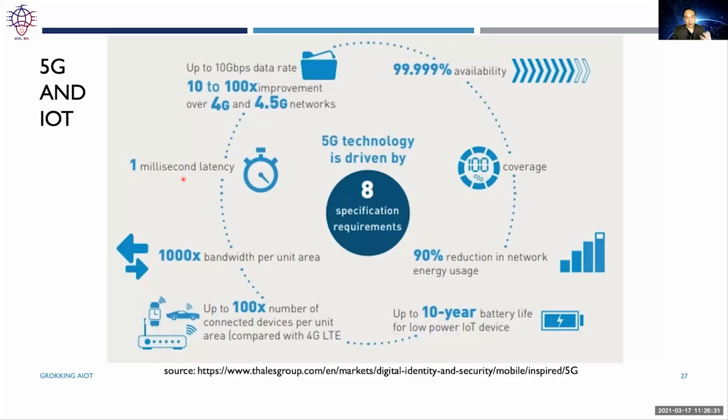So when the information has been processed after it's been read in from the various sensors on the net, large latency when we try to control it with some sort of actuator leads to instability in the control. That means you tend to overcompensate. By the time you want to steer left, the car has already traveled much further to the right than you had originally sensed earlier. That delay between your sensing and your reaction is going to lead to instability.